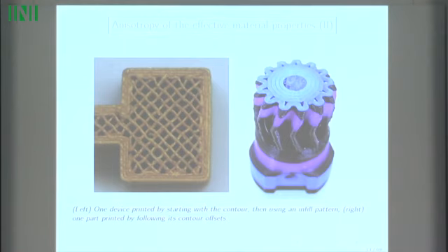And so here, for instance, the typical shape like this will have high resistance to traction in the tangential direction to the boundary, and a low resistance to traction in the normal direction to the boundary, because once this layer has been deposited, it has cooled, and then when the other one is deposited, there are maybe some micro voids between the different layers that are here. Same in the infill, which may be more resistant to traction along the rasters than in the normal direction to the rasters, which are here.